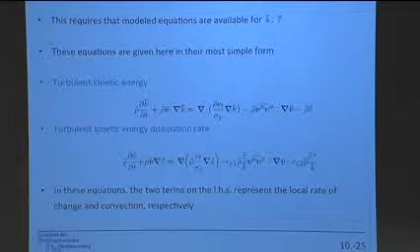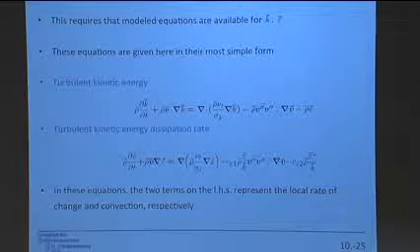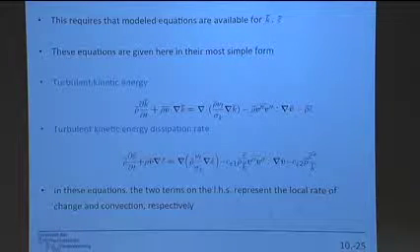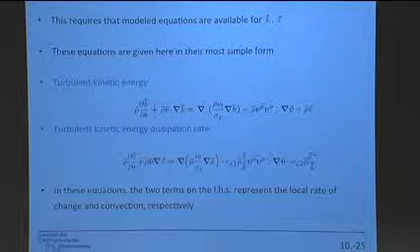The equation for k can be derived actually relatively easily, and the models for the unclosed terms suggest themselves. What's interesting, if you derive that equation, you see a few transport terms again. A convection term, this would be a turbulent transport of the kinetic energy. This is how the turbulence moves itself around.